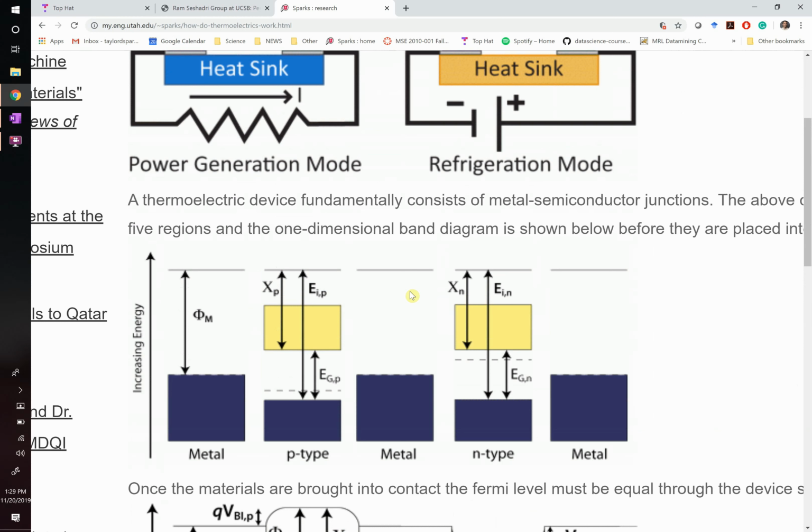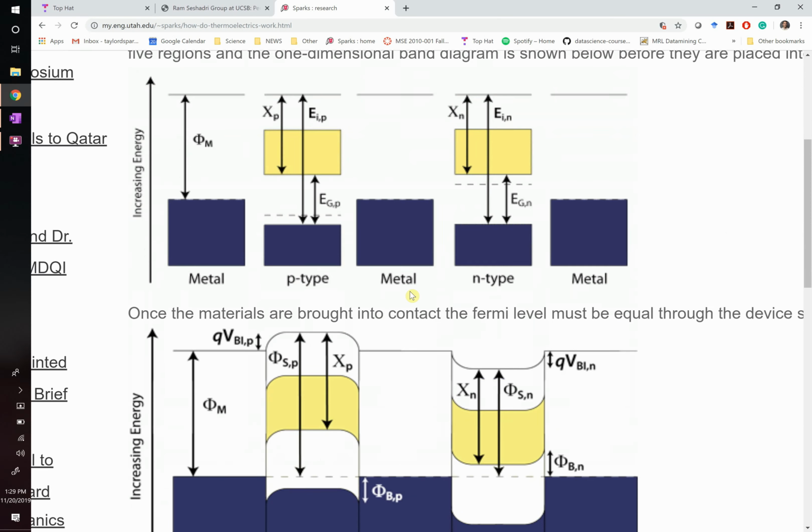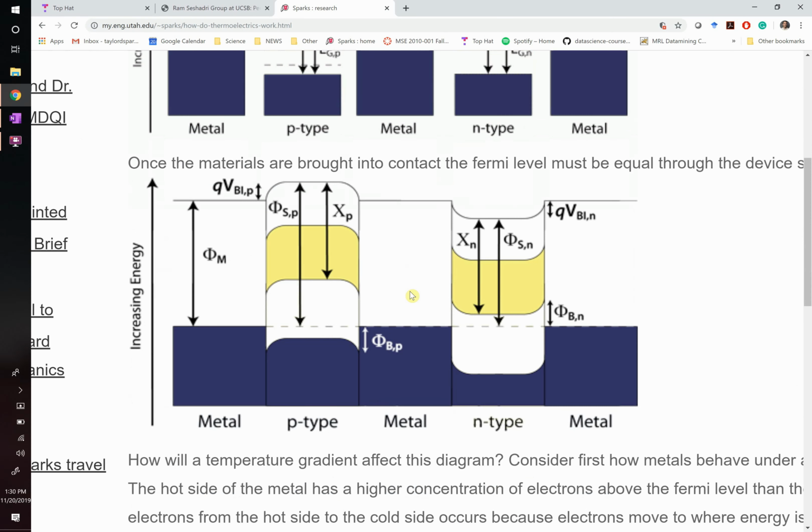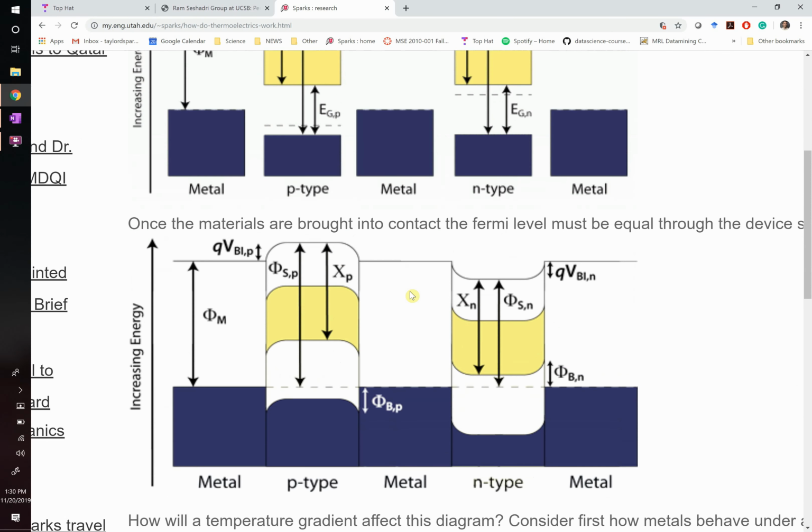So this Fermi level, represented by this dotted line, when you put this material together, literally you press it together, under equilibrium, this dotted line has to become equal everywhere. And the only way to make it equal everywhere is to get what's called band bending happening. For this dashed line to be constant throughout the device, these bands have to bend a little bit in funky ways at those interfaces, okay?